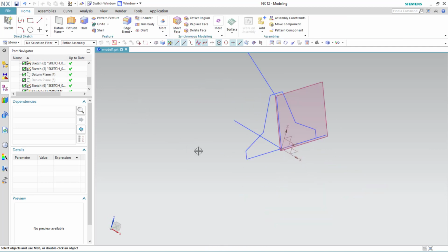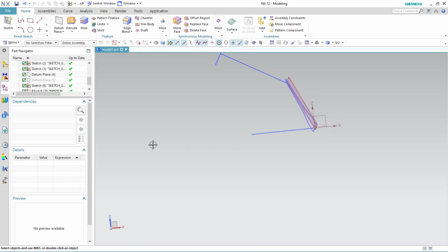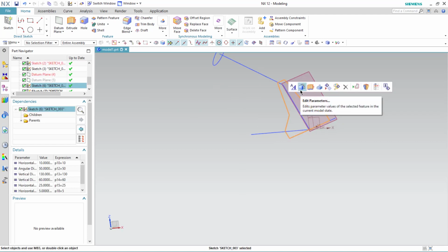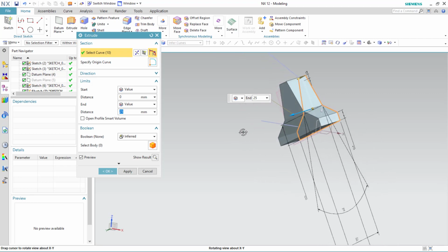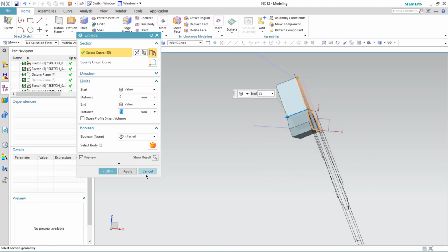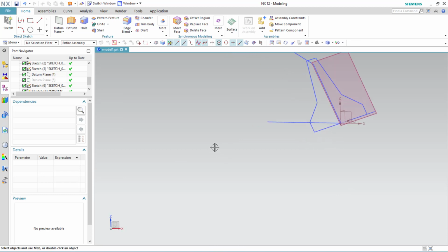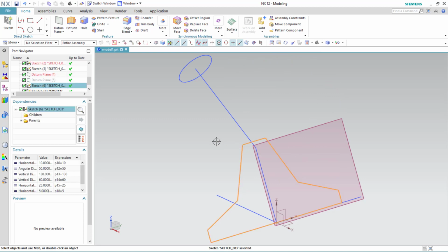Now to extrude it, I would like to utilize the tool called extrude. We already have it here in the features tab. So we have all these boolean operations. We'll see how exactly we need to deal with that later as well. Just select the sketch, and from the quick access tool we have this option, that is extrude. Just select it, and you could see the extrude is along the plane, but I don't want it. I particularly want it to follow the horizontal line I have created.